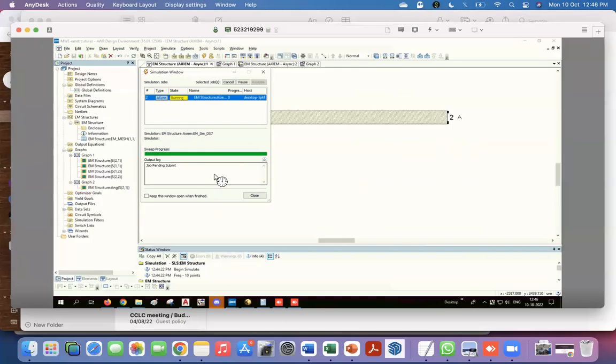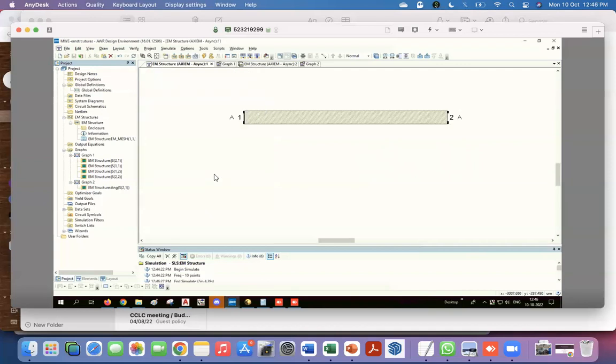And sometimes you might be impatient that, okay, the simulation is taking too long, so I will just reduce the mesh size. We haven't seen how to do that, but there are some default settings which tell the software that you can use high density meshing or medium density meshing or auto meshing. So you can force it to make the structures coarser, and then the risk is that your results might not be very accurate. But in many cases, you're only looking at trends, and for that it's okay. But if you are trying to get the characteristic impedance to 3 places of decimals, which anyway has no meaning, then you cannot really trust the simulations.